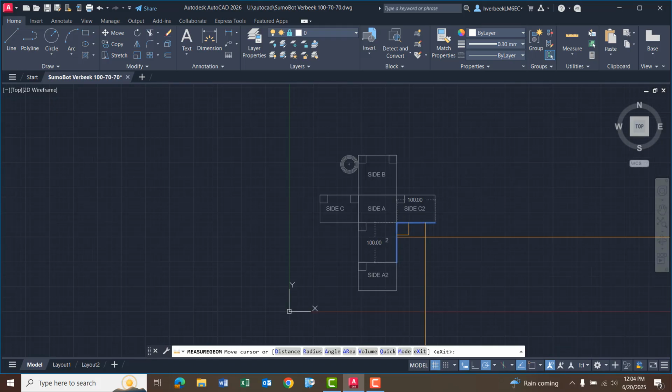You do not have to go as high as we've gone, which is 100 millimeters high. You do not have to go as wide because you might want to have your wheels out. Those measurements are up to you. The strong suggestion is that you go up by 10s. If I want to get skinnier here, I can go 70 or I can even go 60, depending on how wide the motor is, so you should have measured.